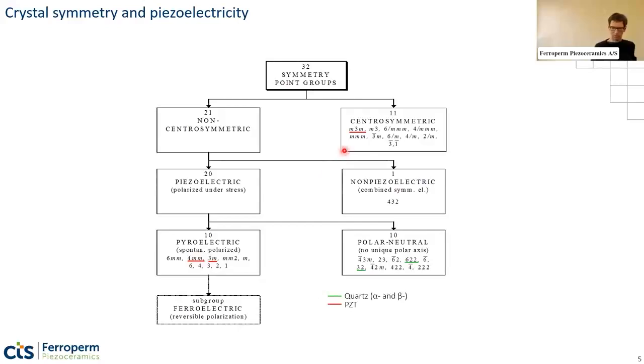If it's above the Curie point, it has this centrosymmetric form, so it's not piezoelectric in this form. And there are also other cases of piezoelectric ceramics with other symmetries. Finally, the structure of a poled piezoelectric ceramic will be this general structure, or it will be equivalent to this one. And then ferroelectricity is actually a phenomenon seen in a subgroup of these materials.